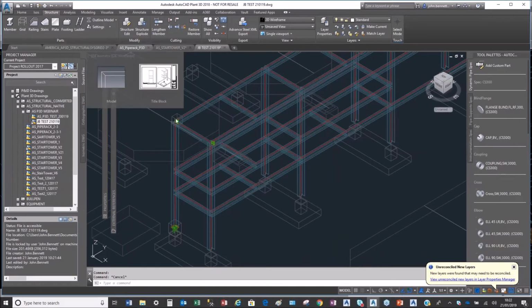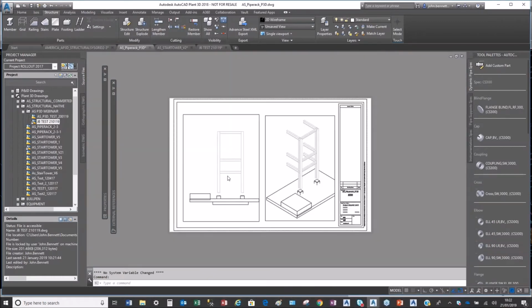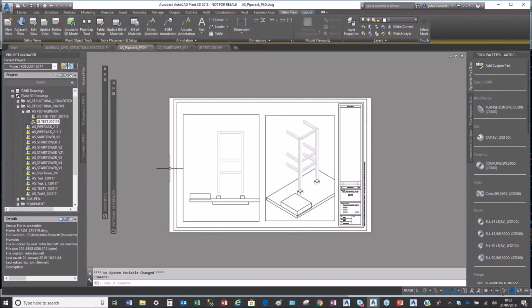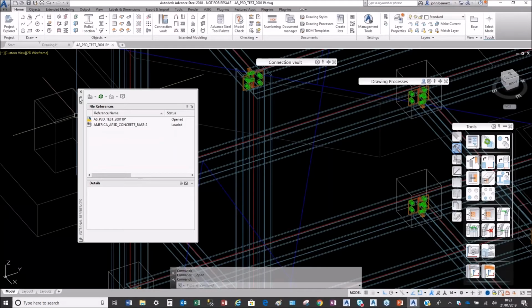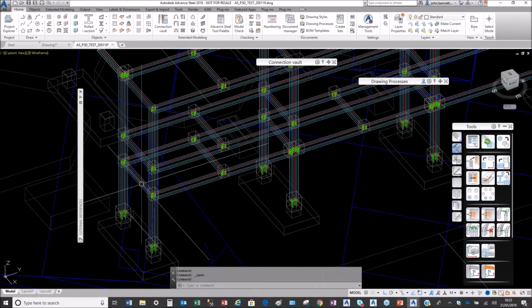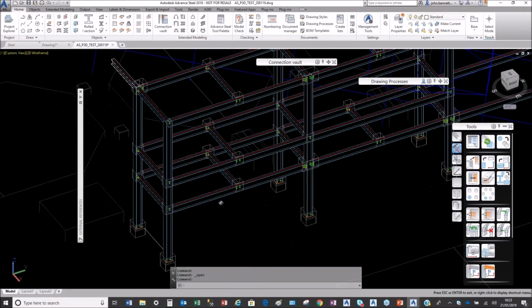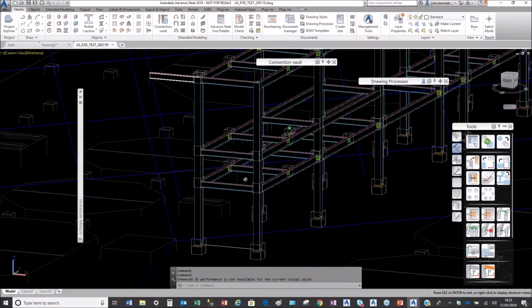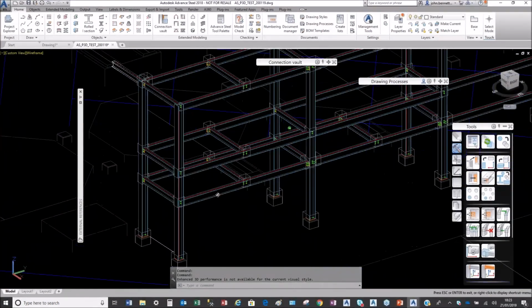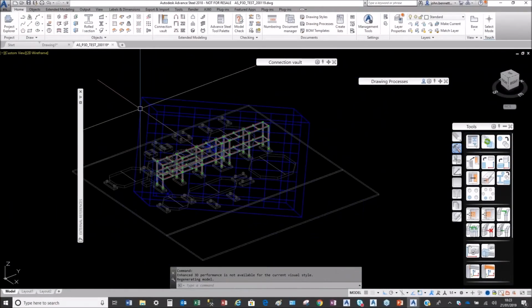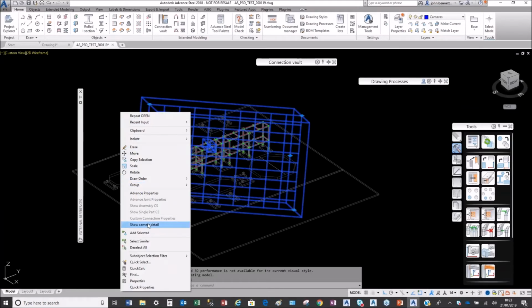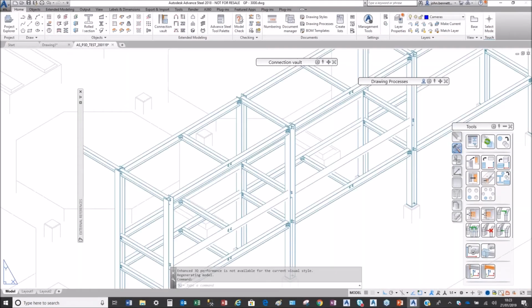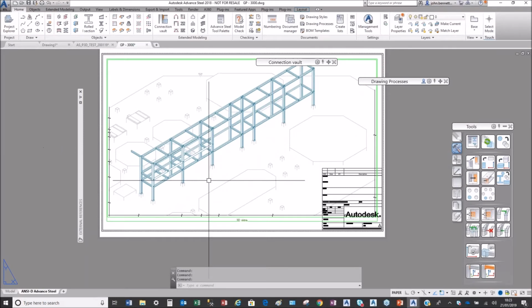So obviously we did a little bit more work on that inside Advanced Steel itself. So that was this model here. I'm just going to go back and show you. I went in and added all the different connections onto that model. And to be honest, it took about 10 minutes to do that. And then I've used Advanced Steel to create a drawing. In Advanced Steel, we have a slightly different method of creating drawings for these elements. So we used a camera, which was the blue object that I just picked, and this will produce a drawing.